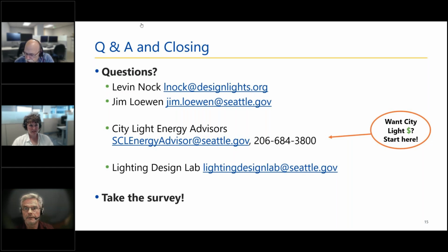Levin, you had a chart that showed the lighting being integrated to the building. Another application is the security system. So if occupancy was triggered and people are in a space that they're not supposed to be in, then security, whoever's monitoring, would pick that up and go check it out if nothing else. Yes, and that can also help when you've got the lights on occupancy sensors, as well as showing up with a message, hey, nobody's supposed to be there. Like whoever is there, the night guard or whatever, can see, hey, that light over there should not be on.